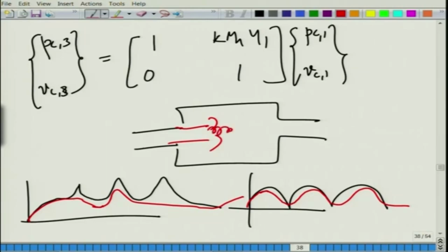There will be vortices being shed which will be interacting with the duct and will create a lot of noise. So, all these things are very classical ways of predicting the losses that will be generated, but then one really has to develop newer expressions for the actual flow situation when you have a non-zero mean flow and the flow is allowed to expand suddenly. It will actually not be very productive, it will be counterproductive, especially when your muffler shell is very thin and it radiates noise outside, and the transmission loss of course will also come down because of this.